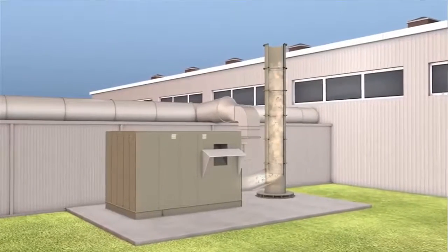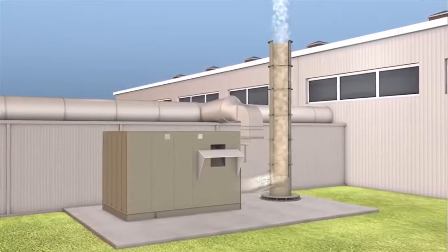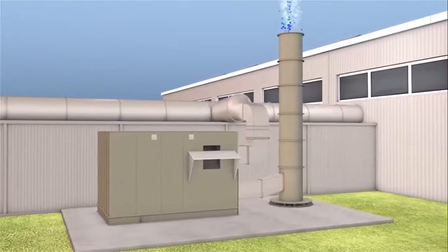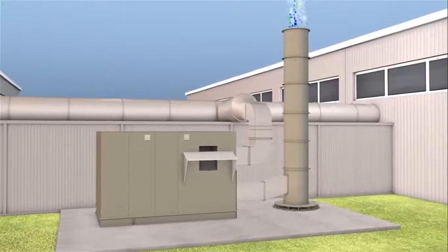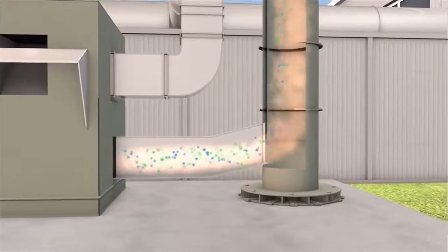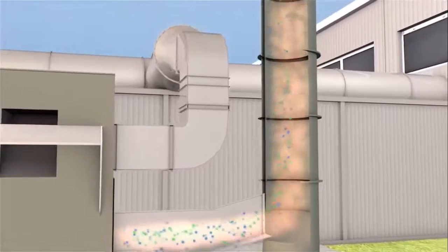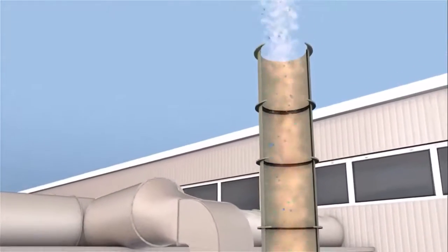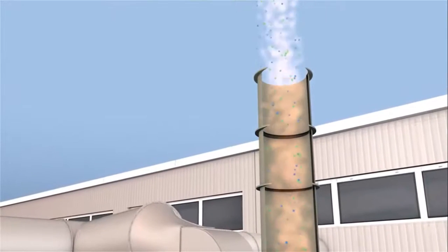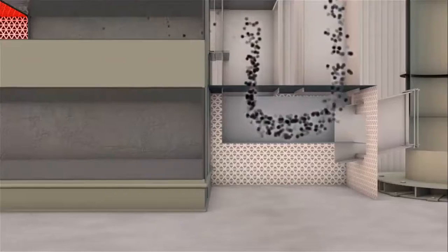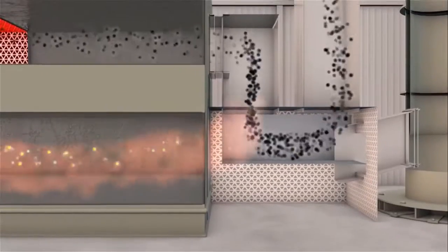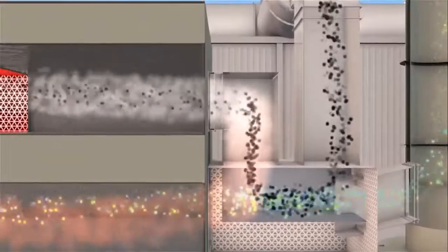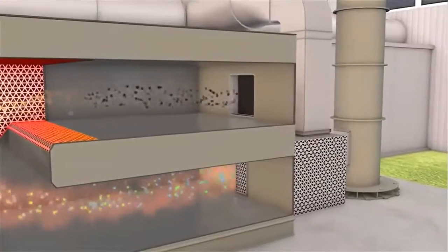Thermal oxidizers are very effective, with a greater than 99% destruction rate. However, they are not as thermally efficient. A straight thermal oxidizer will lose all the heat energy employed during oxidation. However, there is a simple solution that modifies a straight thermal oxidizer and can make the system more energy efficient. By implementing a heat exchanger, existing heat can be captured or recuperated to be reused within the system.